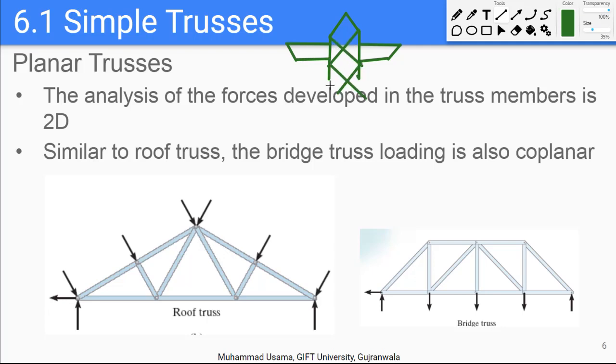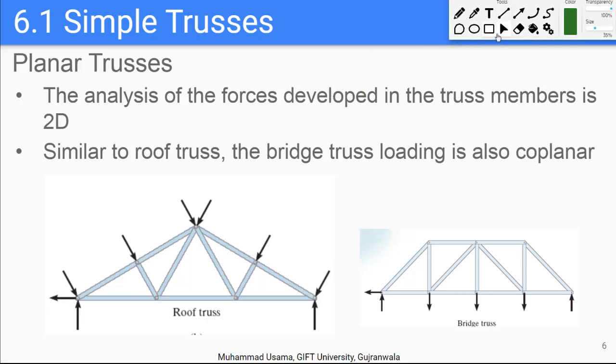These structures which are made out of trusses are easier to assemble, and also easier to dismantle, because this whole big structure can be broken down into these smaller members, and each member does not weigh that much, and it's not very long, so it can be easily transported. So that is a practical reason why many structures are made out of trusses.